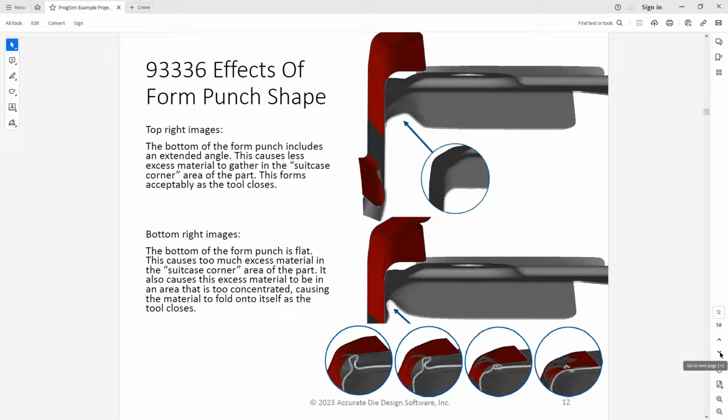There's a part where you can kind of see the X-ray through your tooling. You can actually stop a quarter inch before the tool closes and see the overlap starting to happen. You can start to see that if we hit this leg a little earlier, then that wrinkle wouldn't be happening out there. In real life, you can only see the closed or the open state of the press, so it goes from one state to the next, and there's just a jump. You don't see how exactly the material flowed, so being able to see the movements happen here is really eye-opening on some parts.